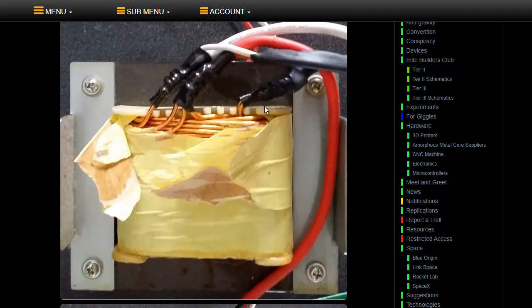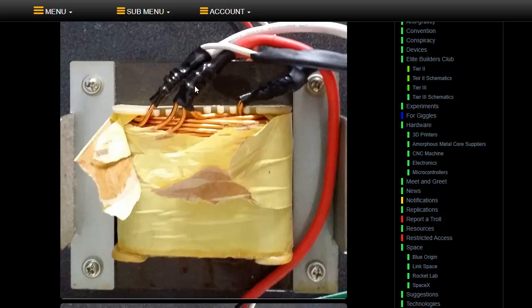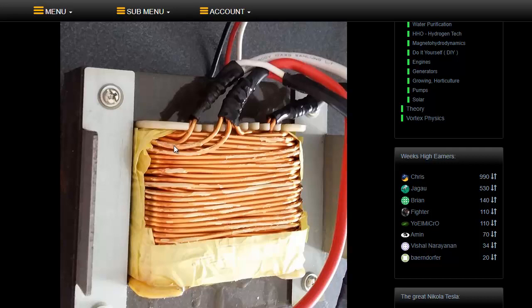This is a transformer. I've got quite a lot of these transformers. It's out of a UPS. Red obviously is the 24 volt positive. Obviously the white and the black there are switched. That's the MOSFET side, so it's a half bridge if you like. And you can see here, there's one wire there, and they come up into the same terminal. So this transformer is a parallel wire or bifilar wound transformer by the very definition.